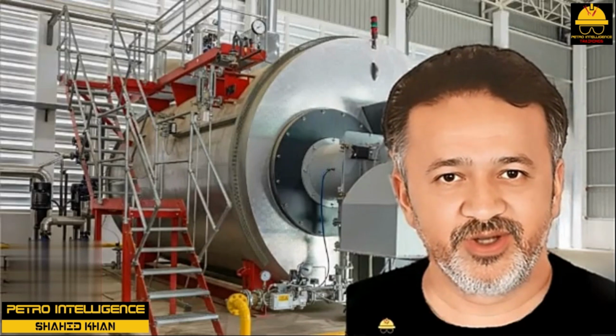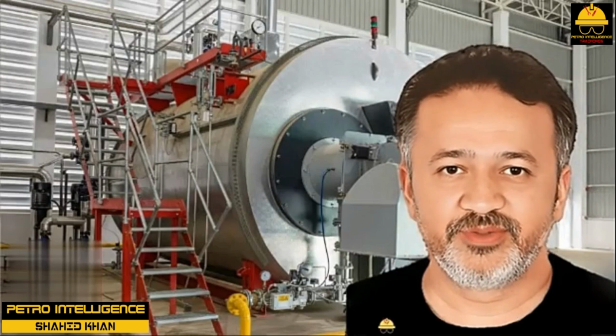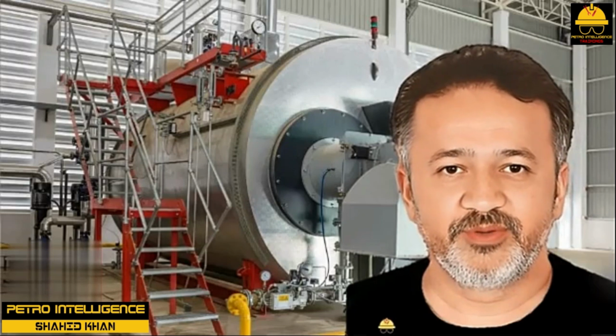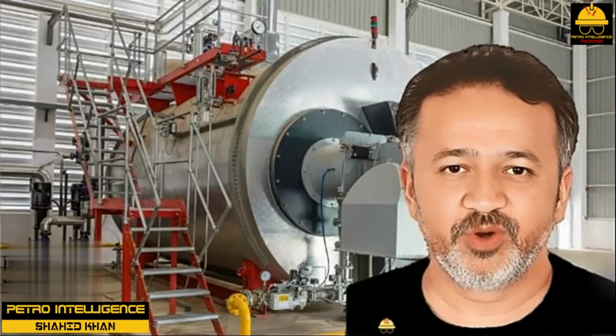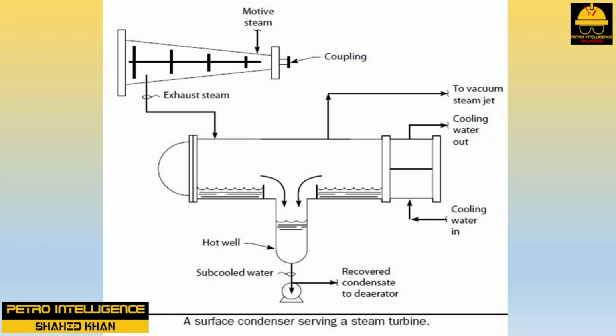The surface condenser is an improvement on the barometric condenser, because it permits recovery of clean steam condensate. Other than this factor, the old-fashioned barometric condenser is more efficient than the more modern surface condenser. This picture shows the type of surface condenser most widely used on older steam turbines. Note that it has both a vapor and a liquid outlet.